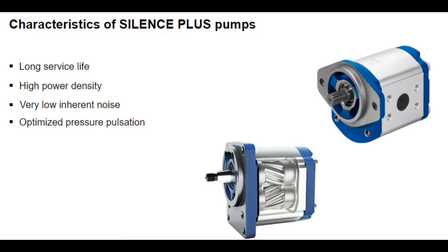Hydraulic fluid leaks from the pressure side to the suction side through gaps in the sides or the tooth crests of the gears. This impacts the efficiency of the pump. Limiting these losses requires greater engineering effort. However, the aluminum housing makes the pump sensitive to pressure peaks.